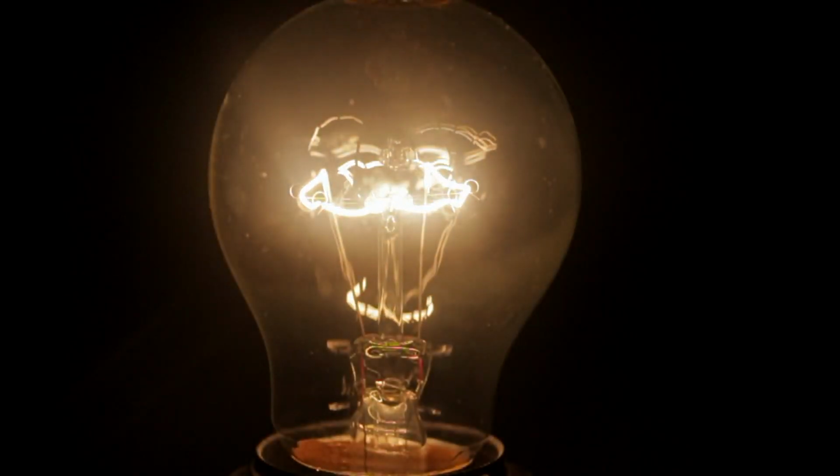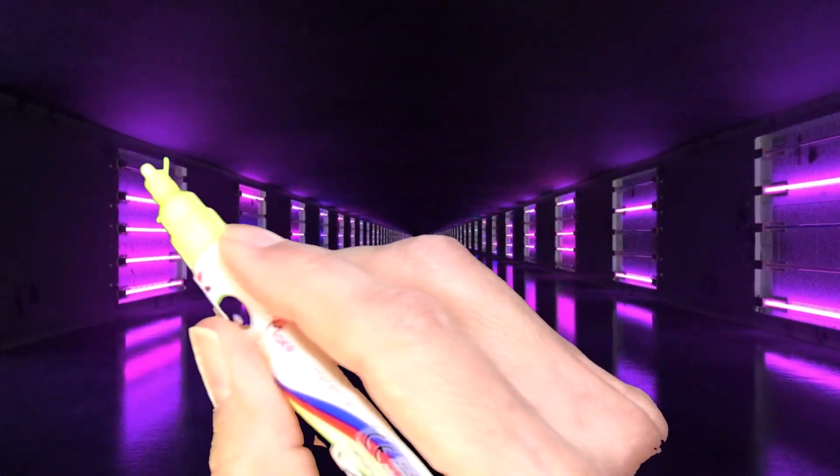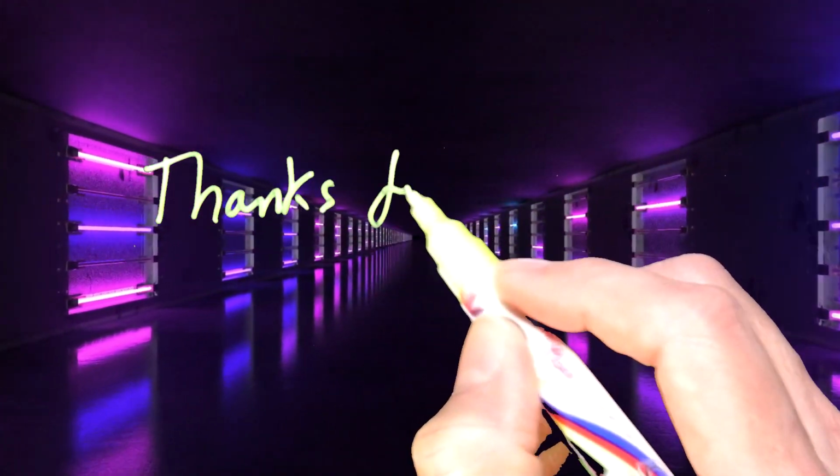So in conclusion, bulbs need a certain voltage to work, and they won't work properly if the voltage is too high or too low. You have to match the bulb to the supply voltage correctly. LEDs need a specific current to work, and the current is determined by the supply voltage and the series resistor together. So they can work from a wide range of voltages as long as you use the right value series resistor. I hope you found that useful and enjoyable.